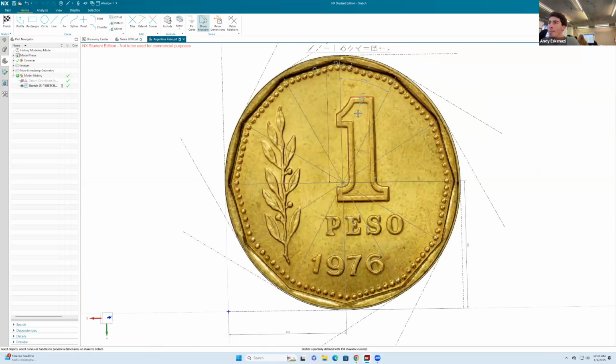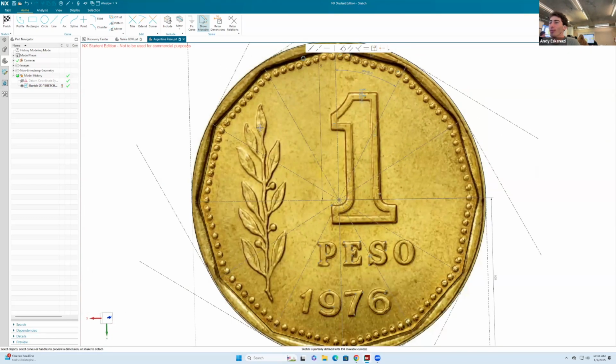So we're almost done. Now, actually, we are gonna do the flowers, but only the exterior part of the flowers, I promise. This one might be a little bit more, actually, I'm not sure it's gonna be as difficult, but the key, as you probably started to notice with me doing this, is that I don't always use a single spline. I use multiple ones. Because if you do everything out of one single spline, it's gonna be a mess. I'd rather create a couple, especially when there's a drastic change in curvature.